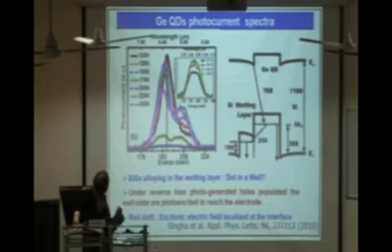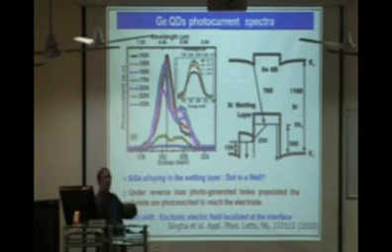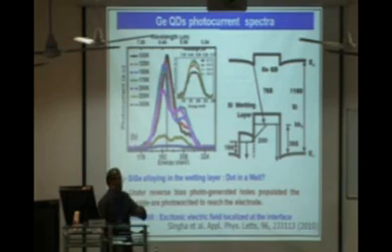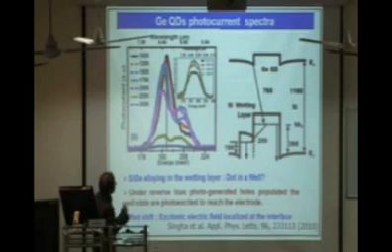And as you see, this works at room temperature because with these quantum dots the leakage current is very, very low. Of course, the noise is very high, but as you cool them, their photo response is very, very high, and this gives rise to detection. And this works at a very low voltage. Normally, with a photodetector you always have to bias it, but in this case, even at a bias as low as 0.1 volt, it gets a very good photo response.